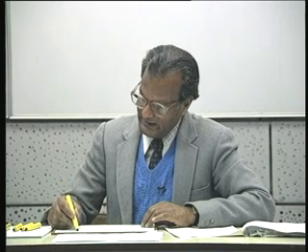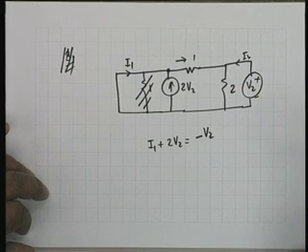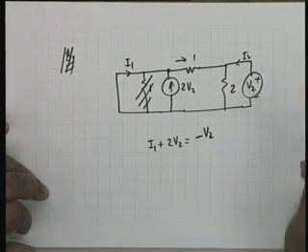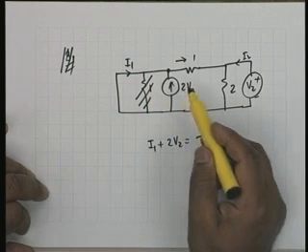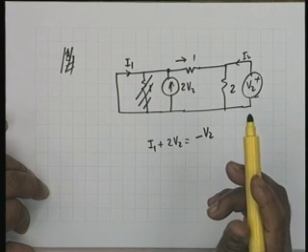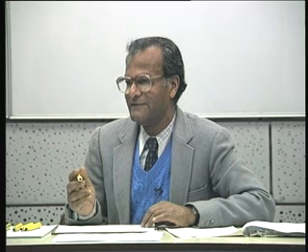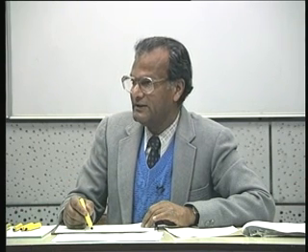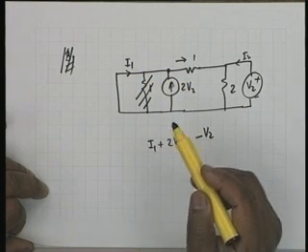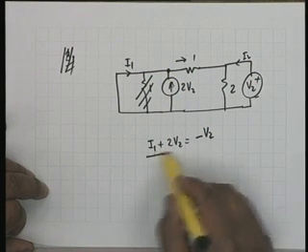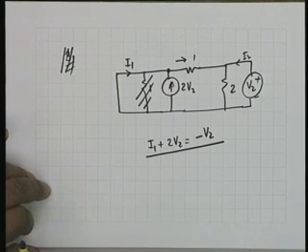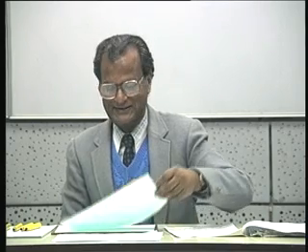But there is a current generator, sir. It is a current generator. So generated currents are independent of the short circuit. Correct. But his question is, shouldn't I1 be equal to minus 2V2? No, because there is an addition because of V2. That's right. There is an additional current going here. These are not the only two currents. There is a third current. And we have taken care of it by writing KCL at this particular node. KCL, yes. I stand corrected.